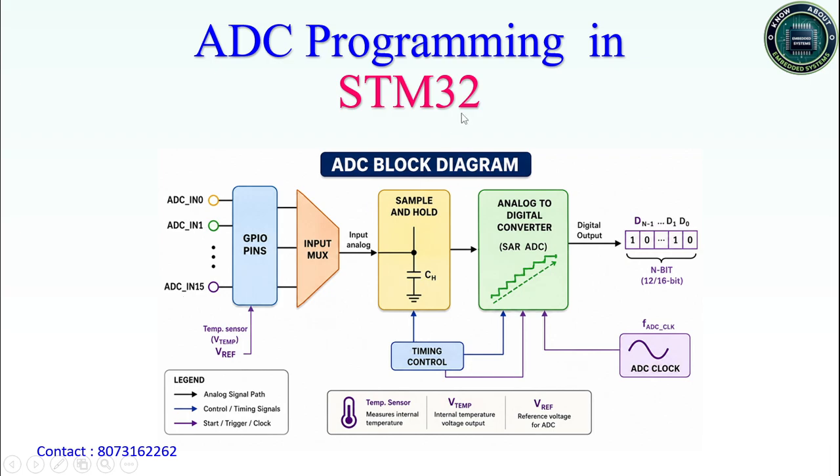So in STM32 microcontroller, we have SAR ADC, and this SAR ADC has 16 channels. You can see here this point. So there are totally 16 channels available, and along with that there is a built-in temperature sensor. You can see this part in ADC. In this microcontroller, there is a built-in temperature sensor also available. So we are going to develop a program to read the temperature data from the microcontroller. Okay, so now let us continue here.